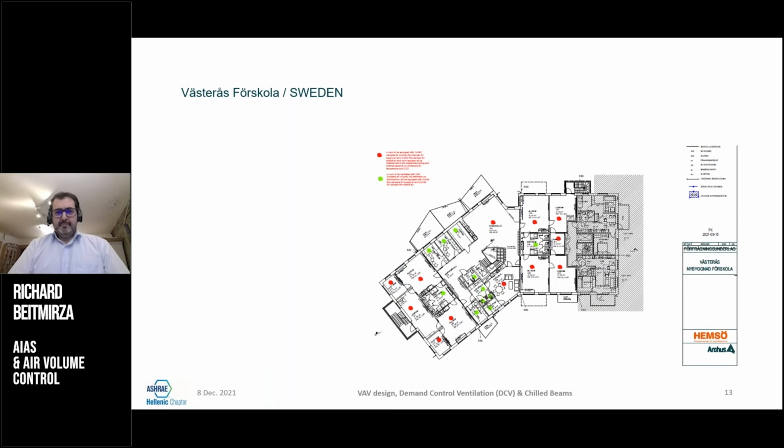In these cases, we have to work very precisely with pressure sensors in order to make sure that we maintain the right pressure and the right volume throughout the building, because it is one air handling unit for 2 floors, and it's different rooms and different requirements, and we have variable loads and constant loads. It is very easy to do, but it has to be done in a fashion that we make sure that there are no errors in different loads.